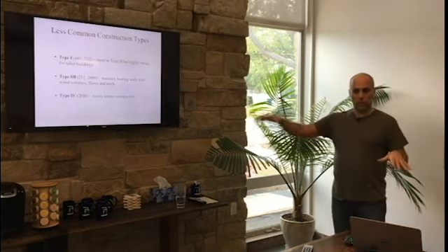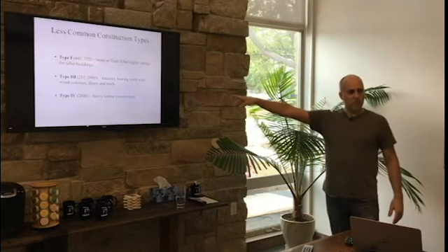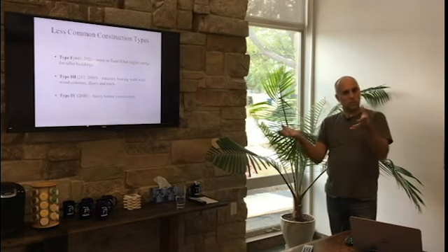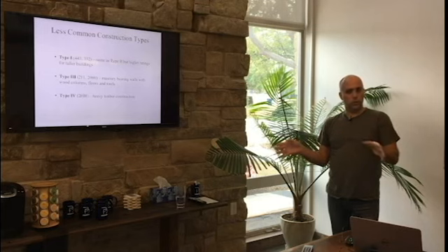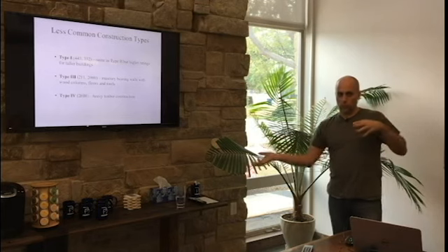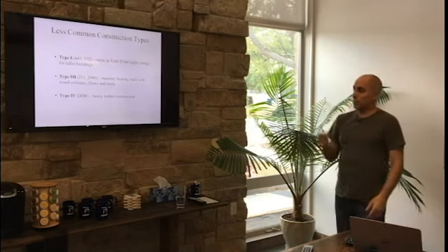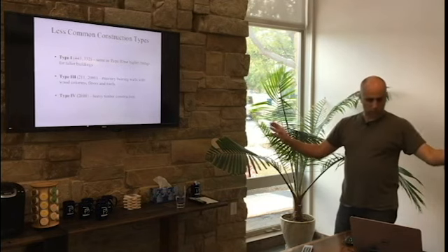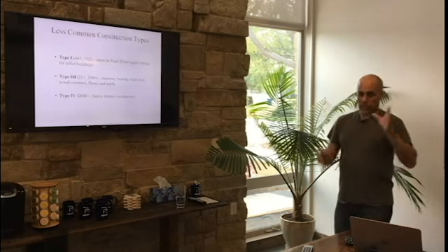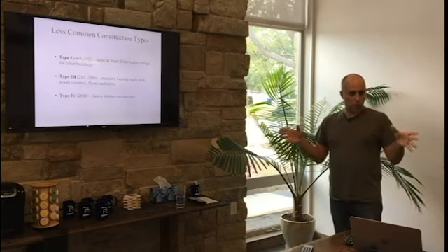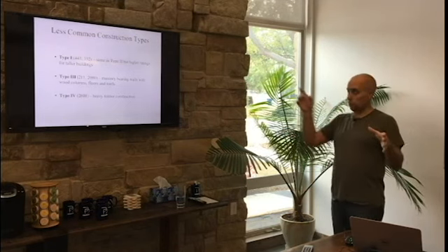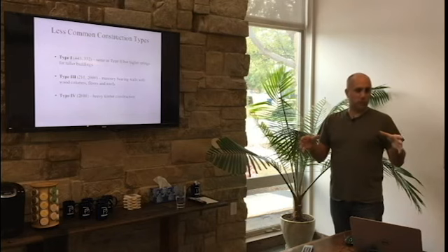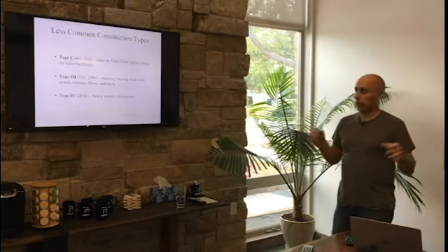Now, in the 2000 code, you're not allowed to mix between any construction type. I.e., if you're using type 5, you can't use heavy timber. Well, it's heavy timber, so I can. No, under the 2000, you can't mix and match. You can't just use one from one type and another. It's all or nothing, period. If it's wood, it's type 5, period. So that means if you have a 20 by 20 column out of solid Douglas fir under type 5, you are putting gypboard on the outside of it. Talk about a shame to do that.